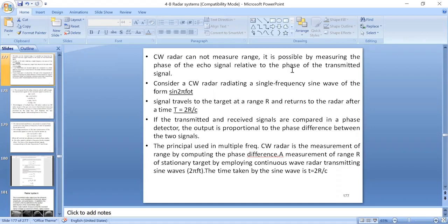But instead of transmitting one pulse, compare it with an integration of radar pulses. While analyzing the target information and calculating parameters related to the target, you are considering n number of echo pulses into account, and those n number of pulses are integrated. That concept is called integration of radar pulses, right?